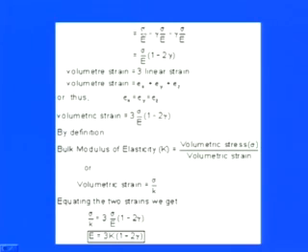If we look at this figure, sigma, sigma, sigma is acting in all 3 mutually perpendicular directions with equal magnitude, and all 6 sides of this cube have equal dimensions, A. So the total strain in one direction, or along one edge, due to the application of the hydrostatic stress, the equal or volumetric stress, is given by sigma by E minus mu times sigma by E.